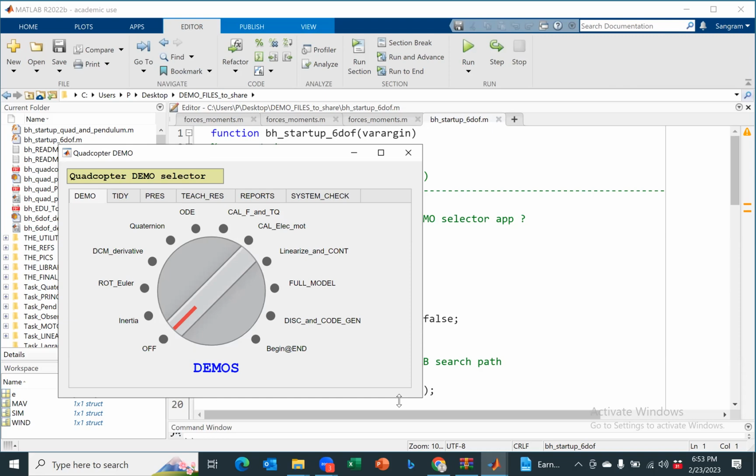For quadcopter, only the values of forces and moments will be different than the fixed wing. Then, if you have an electrical plant and want to do the electrical modeling, just to understand what is the battery, what is the size, everything, you actually can perform the electrical motor analysis. Then you linearize the model and you control it.